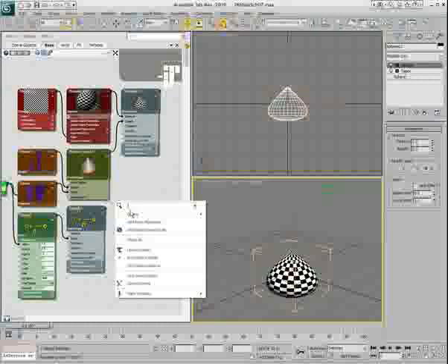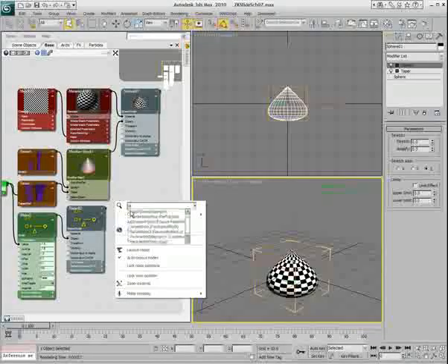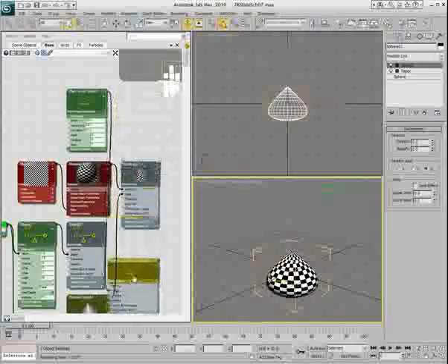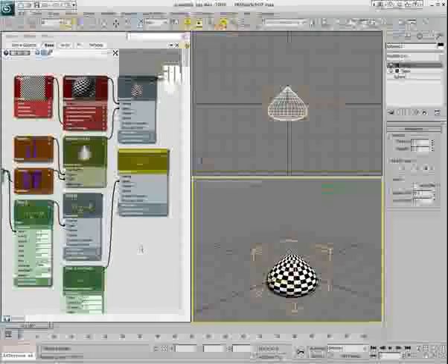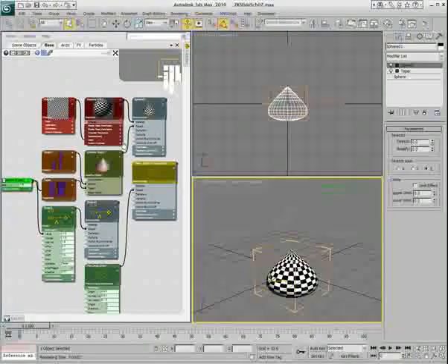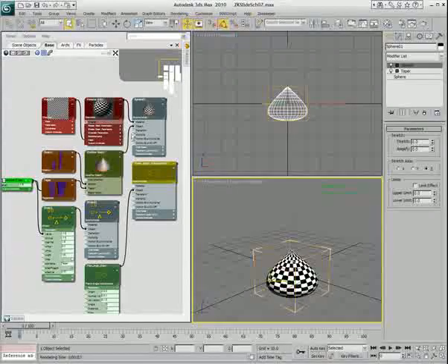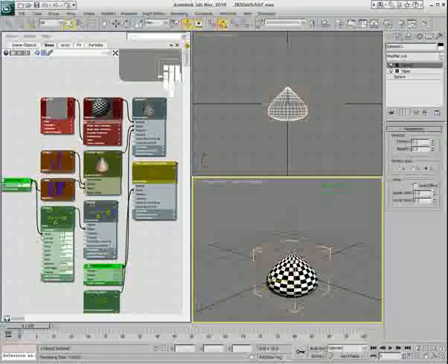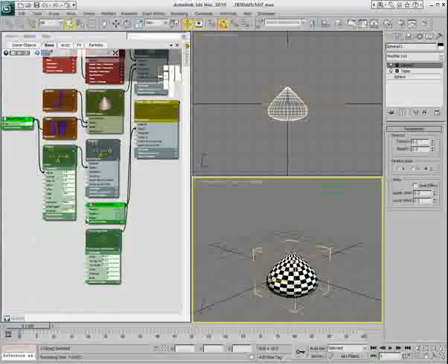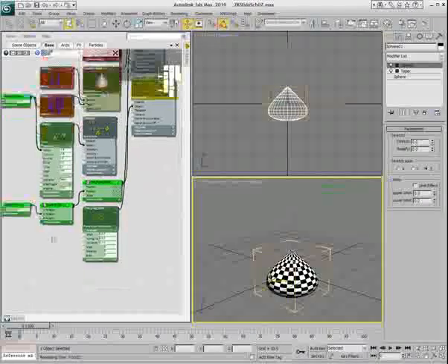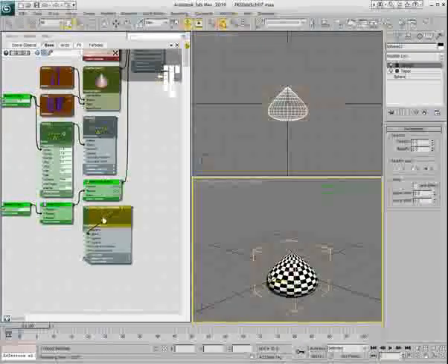And then I'm going to just right click and create a plane angle manipulator. So here's the plane angle manipulator. I'll drag it down slightly, and I want to be working with the transform of this so that I can set that manipulator to work. So I'm going to drag that out quickly. I'll drag out the rotation, the Y rotation. And that's really what I want to be working with.